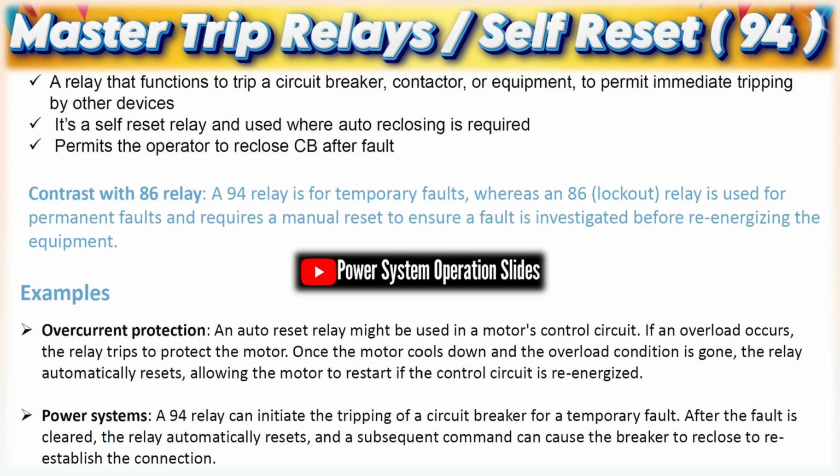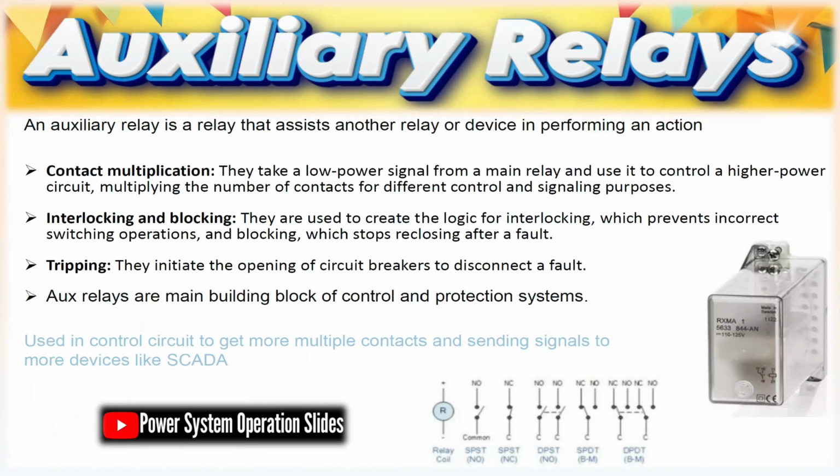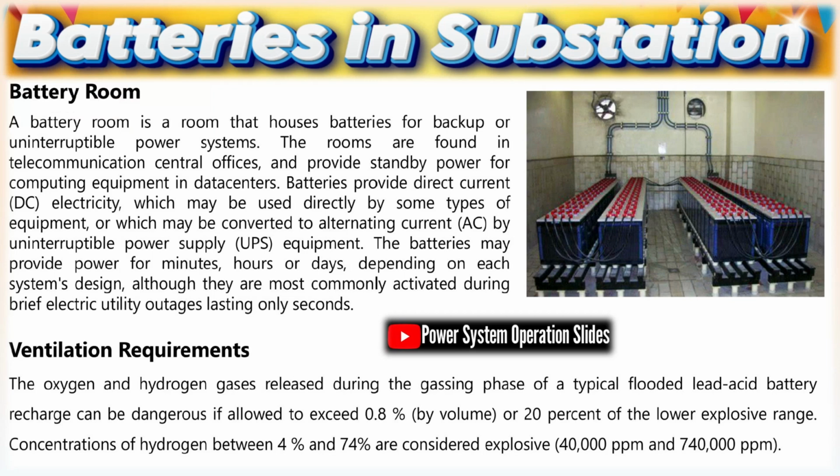PLC, substation communication, fiber optics. Fiber optic communication links PLCs and IEDs with SCADA using protocols like Modbus TCP/IP or IEC 61850. Optical ground wire enhances speed and immunity. It forms the backbone of digital substations.